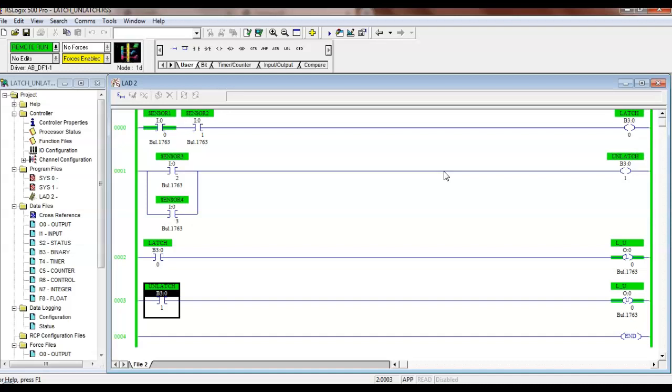And we're doing a little logic up there. We have an AND at the top, only two contacts. So that's something you got to understand, that AND is a minimum of two, right? But you could have a ton down that string, and ORs are a minimum of two.